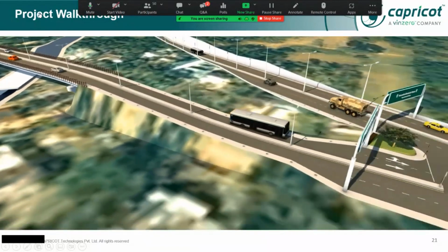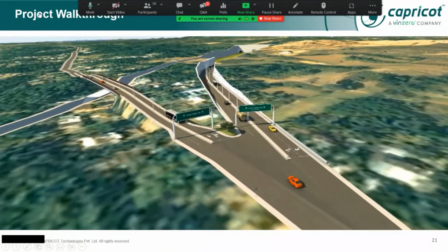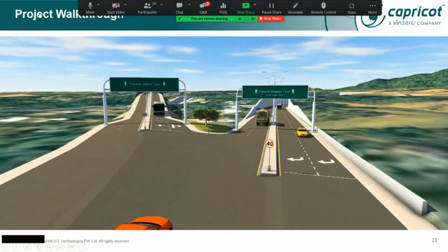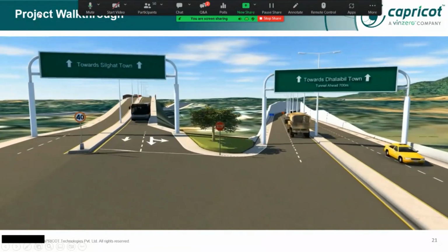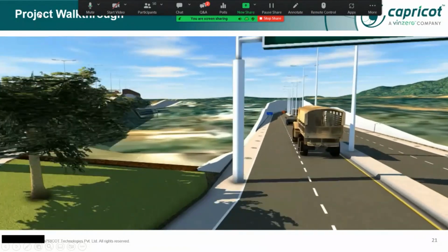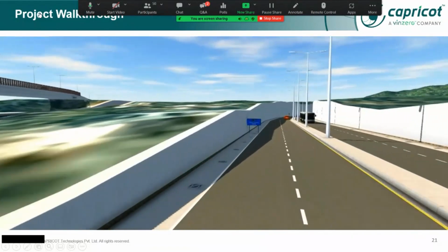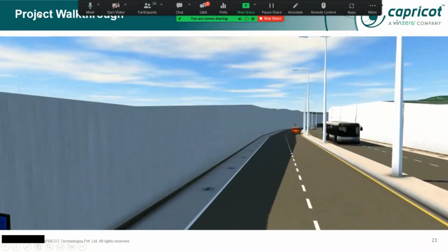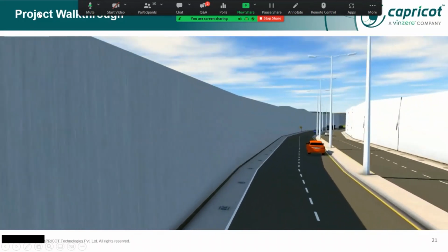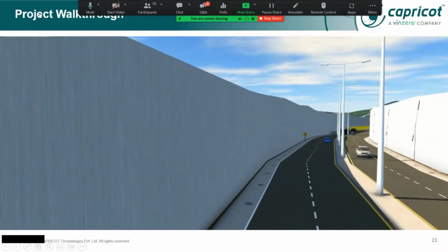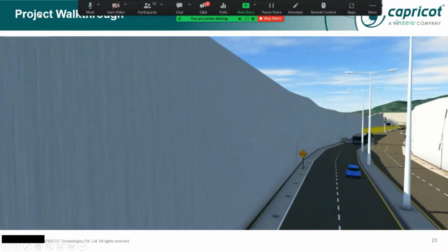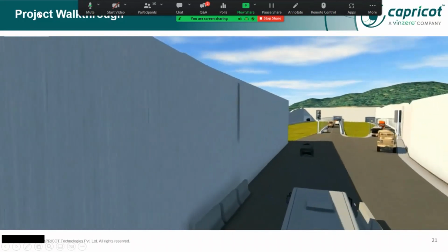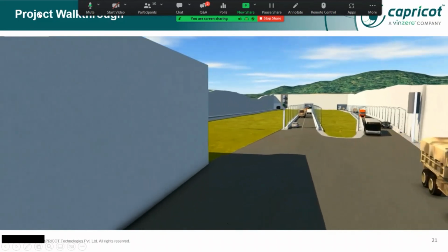The roads which have been modeled and proposed in InfraWorks, that information, for the profile optimization workflow, we have exchanged completely from InfraWorks to Civil 3D, where we propose the vertical alignment of that particular structure. Apart from that, as you have seen previously, our station building has been placed. That station building has been developed in Revit, because InfraWorks has a data source option. And when you are working with the Autodesk environment, you have very good integration between the different AEC suite software. You can exchange information from one software to another.